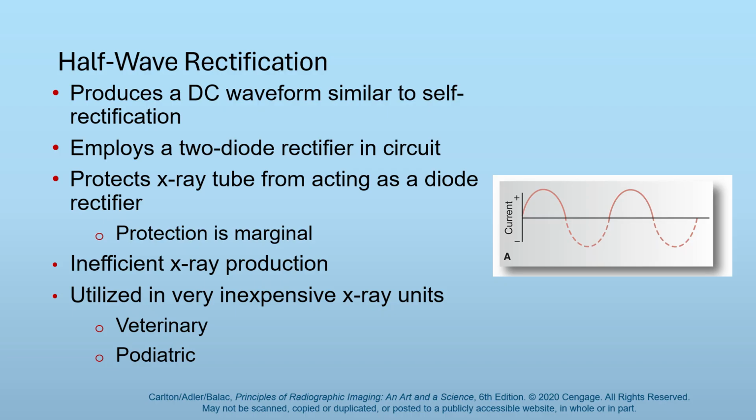Half wave output, basically you erase the troughs. You got 0 voltage when there should be a trough. Okay? So you still get a voltage across the X-ray tube during a crest. It's just during a trough, it's basically the circuit's dead. There is no electricity flowing. That's why those are dotted lines for troughs. The trough should be there, but it's being stopped by the diodes. Okay.